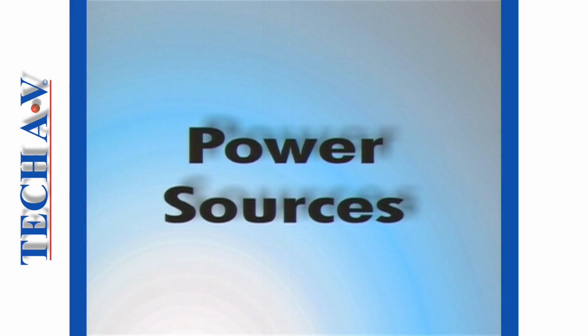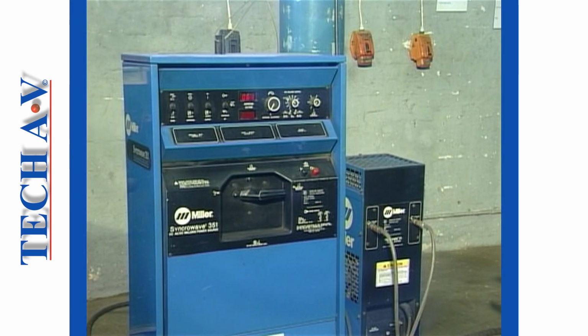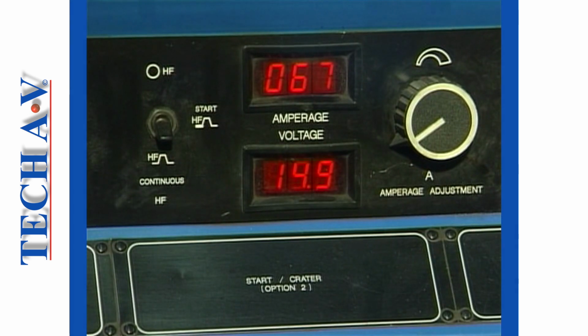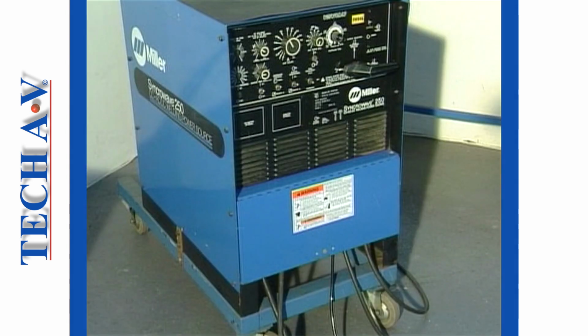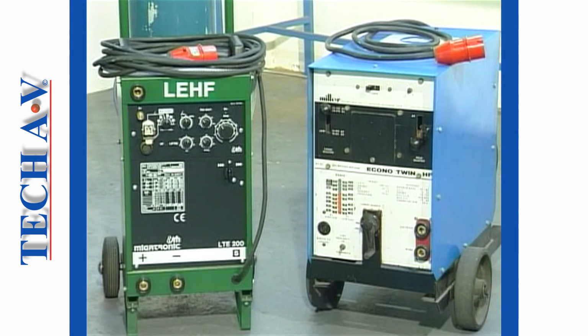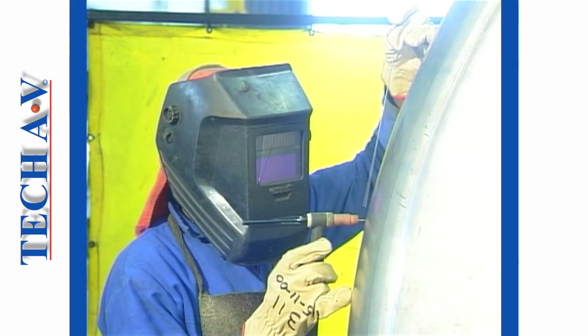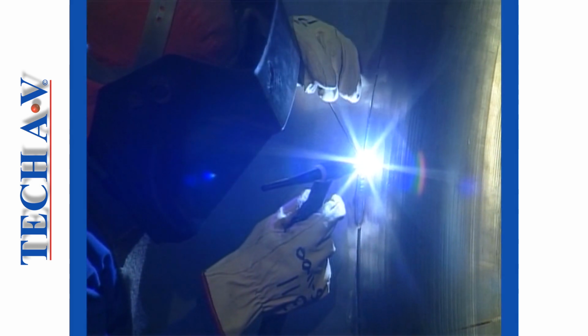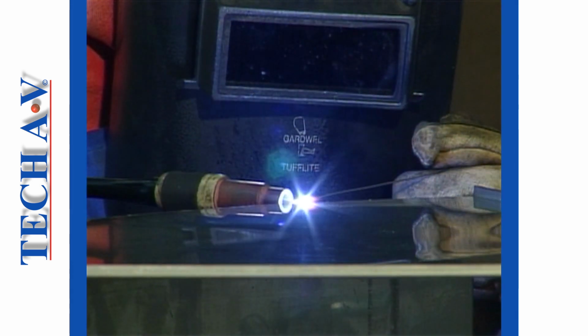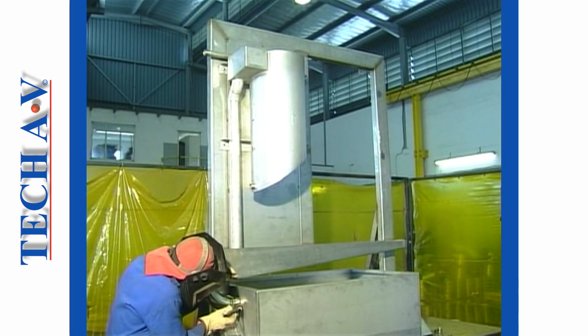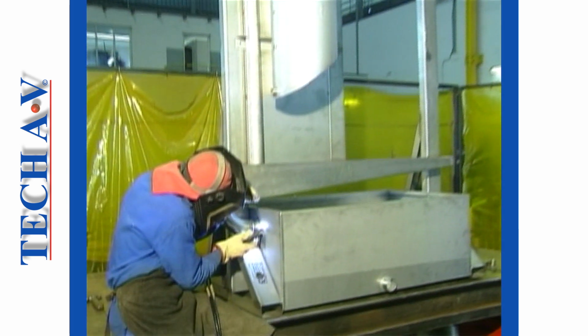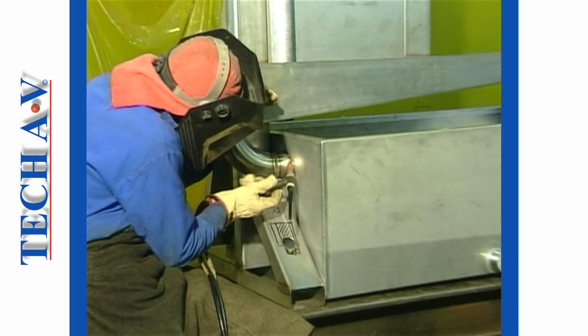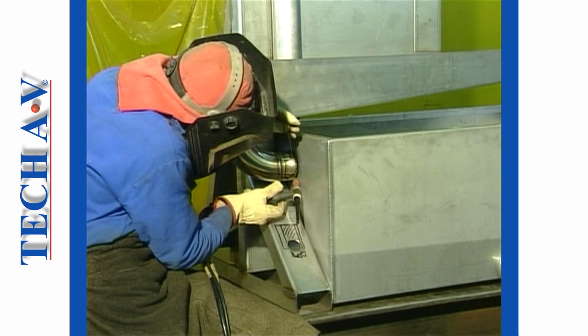Power sources or welding machines suitable for use with the TIG process are of the constant current type and are often produced for use with both TIG and with SMAW processes. TIG welding is used extensively in fabrication and repair processes involving thin gauge metals. In fact, this is the main reason that TIG is so popular. The welding current for such operations rarely exceeds 150 amps, and in many cases, a welding current of only 20 amps is sufficient to effect a weld.